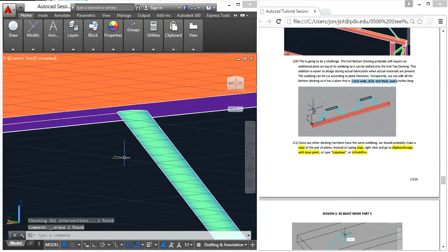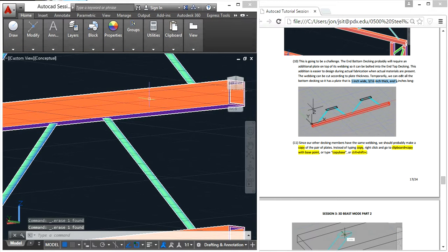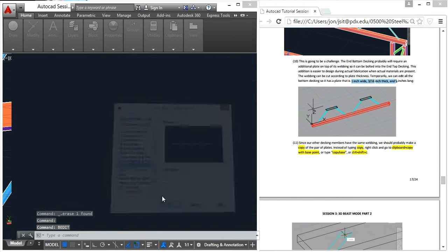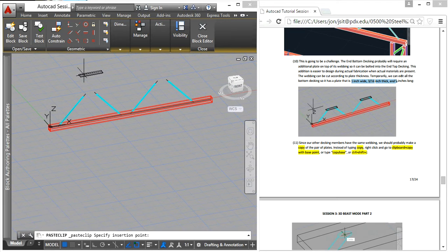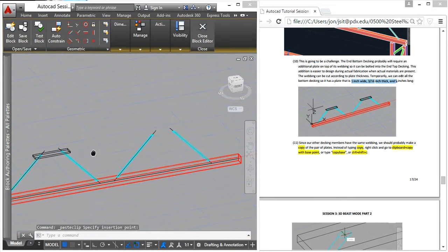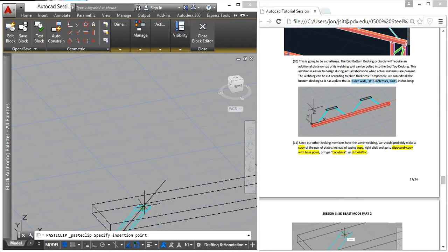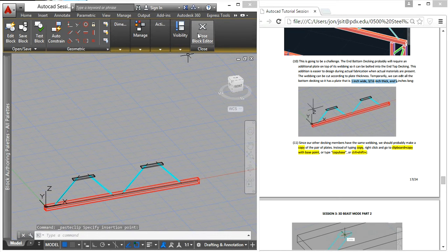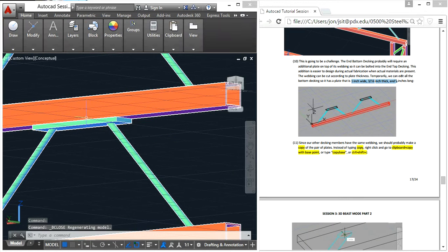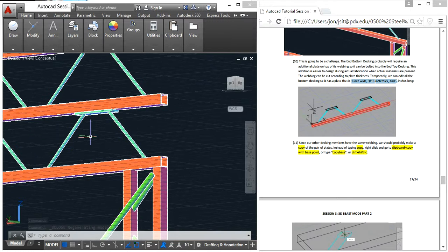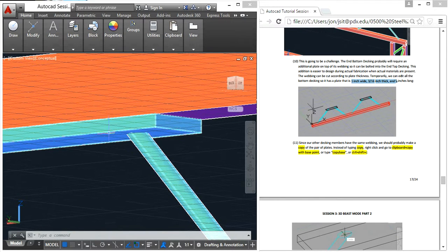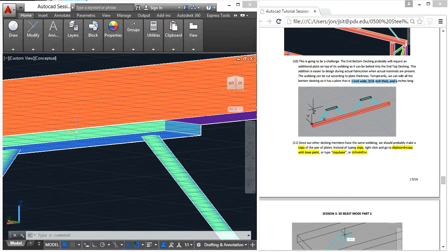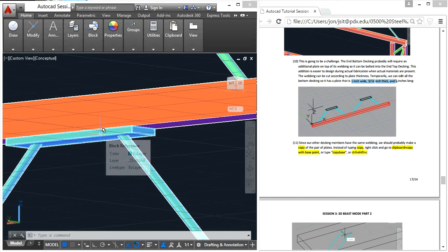Now that I have it, I'm going to delete the existing one. I'm going to delete this line as well, since we don't need it anymore. I'm going to click this, go to edit again, and while I'm in the block editor, I hit Control V for paste, and I can paste right where I want it. You can keep doing that, just hit Control V again, and you get the same base point. We're going to hit close, and then save, and there's your plate. Now this is a little bit more realistic, which is a huge deal. You really want it to be as realistic as possible. You're not going to know this unless you already bought the material. Say you didn't buy the material yet, then you wouldn't know how thick this plate is going to be, so you can always change it later on if you want.